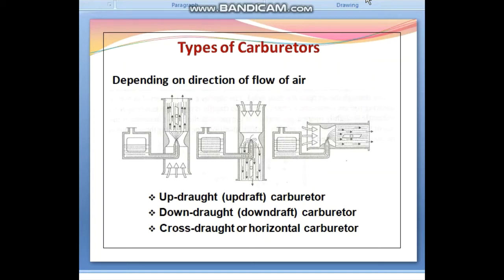Otherwise, the fuel droplets tend to separate out, providing only a lean mixture to the engine. On the other hand, if the mixing tube is finite and small, then it cannot supply the mixture to the engine at a sufficiently rapid rate at high speed.